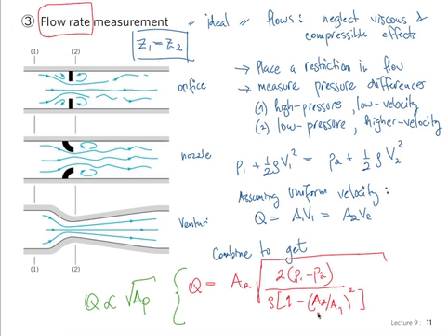So flow rate can be determined by pressure differences, and this is what we use in the lab. And these are devices which are very common, and commercially you can find the orifice plate volume rate meter. You can buy them, and they give you specific data. We are assuming here that they're ideal, but in the real case, there will be a small loss, and the commercially available devices will actually tell you how much that small loss is, so that you can make more precise calculations.